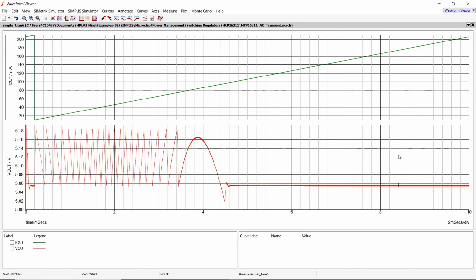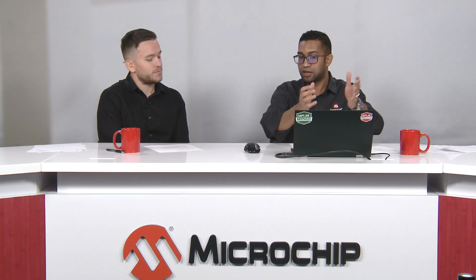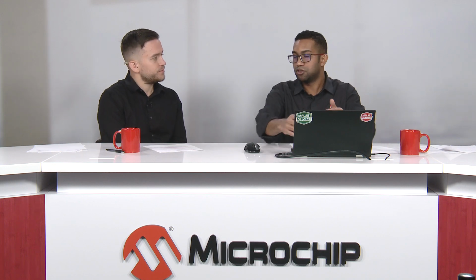Yes. So you might be wondering, well, why did we offer the PFM mode? Well, that's because if you want to do a trade-off between efficiency and ripple, then if you can handle this ripple, the PFM PWM transition allows you probably a more efficient design. However, if you are someone who's thinking, I don't care about that extra efficiency, I want a clean Vout throughout the different ranges on the load, then move to the 16312. Okay. So that's the design decision. That's how the Mindi simulator can help somebody to make that decision.